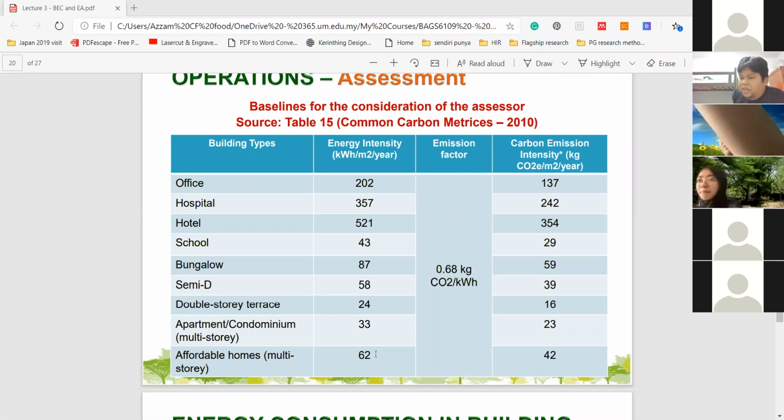And then there aren't enough air curtains to limit the movement of cold air. If you can't put windows or doors to segregate the spaces, then just use air curtains. They can be a bit noisy, but at least they stop the aircon from running out. There are a lot of efficiency measures that need to be done.